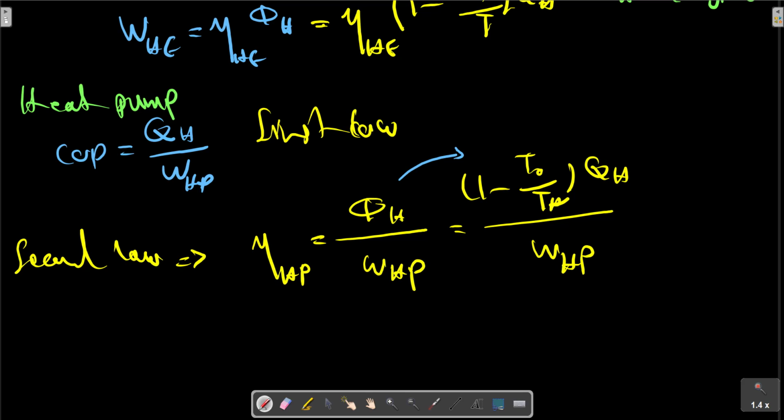A similar but slightly different measure of performance is to look at the exergy destruction terms, either absolute or relative to the exergy input from the source. Consider a more complex system such as a complete steam power plant with several devices. If we do the analysis of every component and find the exergy destruction in all parts of the system, we would then use those findings to guide us in deciding where we should spend engineering effort to improve the system. Look at the system parts that have the largest exergy destruction first and try to reduce that by altering the system design and operating conditions.